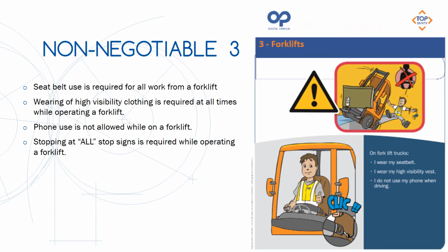Non-negotiable 3. Seatbelt use is required for all work from a forklift. Wearing of high visibility clothing is required at all times while operating a forklift. Phone use is not allowed while on a forklift. Stopping at all stop signs is required while operating a forklift.